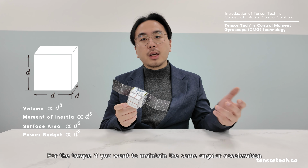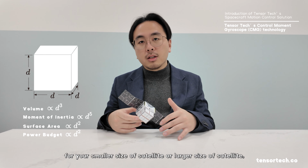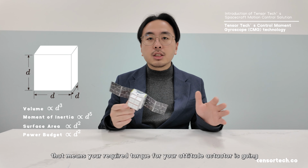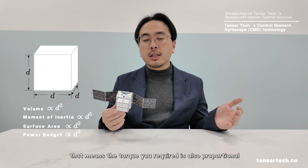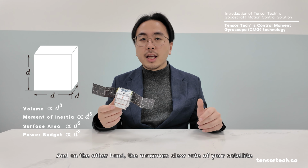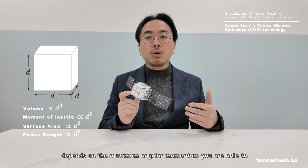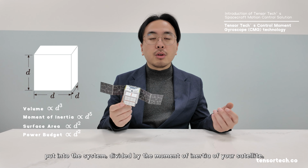For the torque, if you want to maintain the same angular acceleration for a smaller satellite and a larger satellite, the required torque for your attitude actuators is going to be proportional to the moment of inertia. That means the torque you require is also proportional to d to the power of 5. On the other hand, the maximum slew rate of your satellite depends on the maximum angular momentum you are able to put into the system divided by the moment of inertia of your satellite.